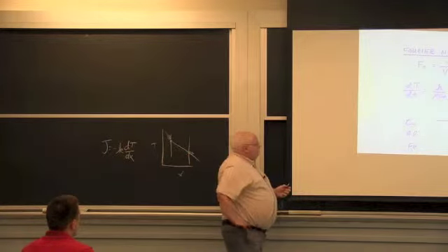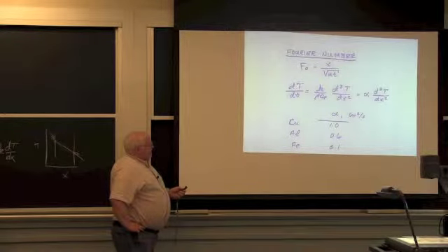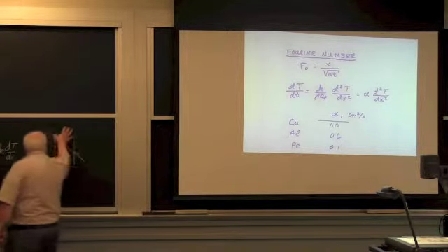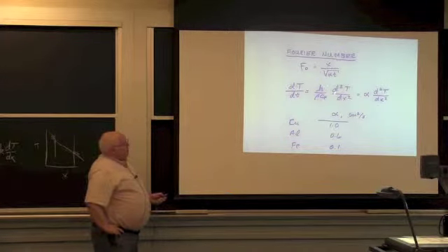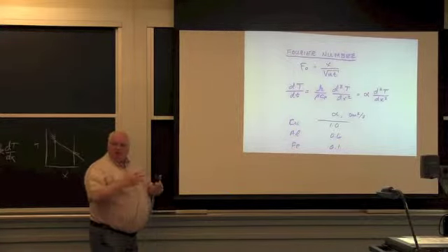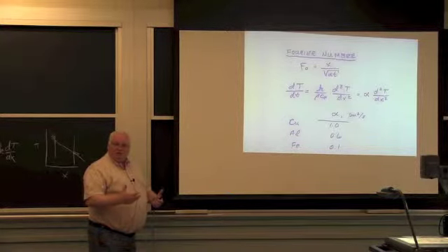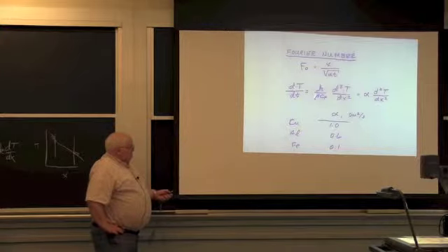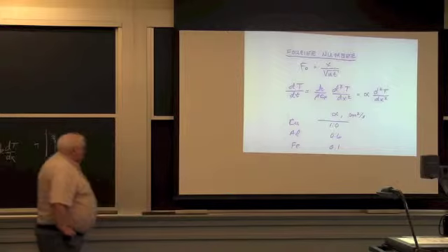So Fourier's first law is steady state. Fourier's second law says the change in temperature with time in this little volume element that I'm going to look at is equal to K, and you have to have the heat capacity and the density in here so you know how much you have. Obviously a foam, you can heat up a foam faster than you can a solid of the same material, right? So you have to have a density and a heat capacity, and the gradient or the curvature, the second derivative of temperature with distance, is the curvature.